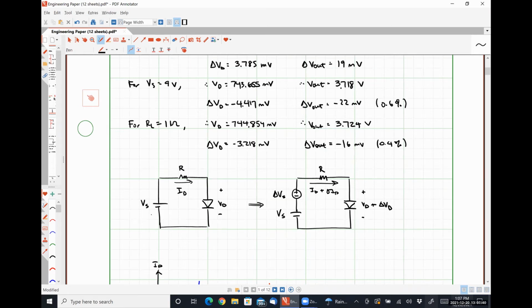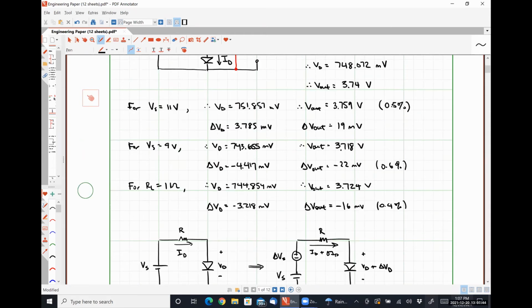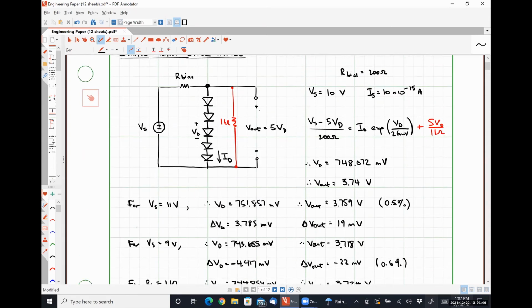Okay. We've obviously already covered voltage regulators, which let me scroll up here real quick. This was an example of a voltage regulator. In practice, it would be much more likely for us to see a well-defined Zener diode in a reverse bias configuration than 5 normal diodes in a forward bias configuration. Nothing inherently wrong with this. It's just a Zener diode does the same job with only a single component. We just have to make sure that it's giving us the right voltage.